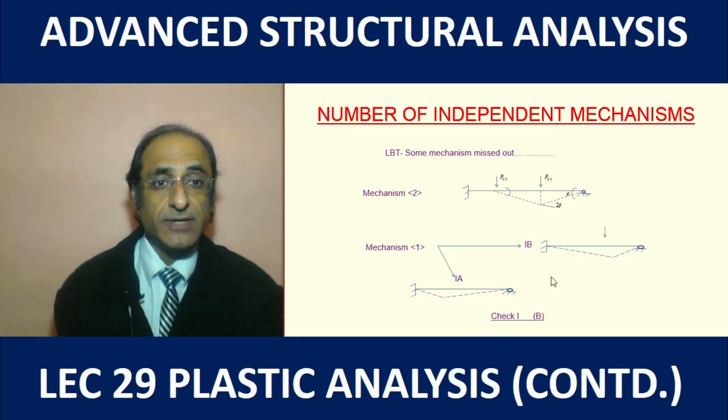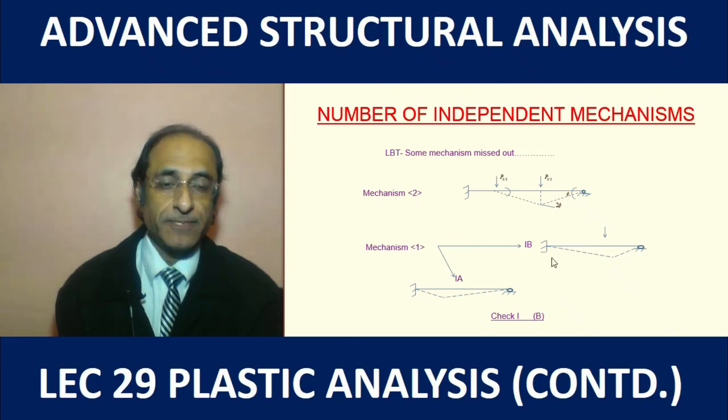So basically the equation had given us the possible mechanisms as 2, but within this particular mechanism number 1 there are two possibilities. This involves hinge formation at the support, and the other location of the hinge could be either B or C. We must check this failure mechanism now.